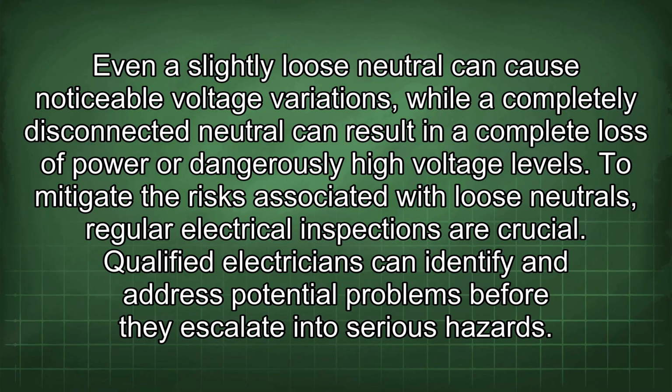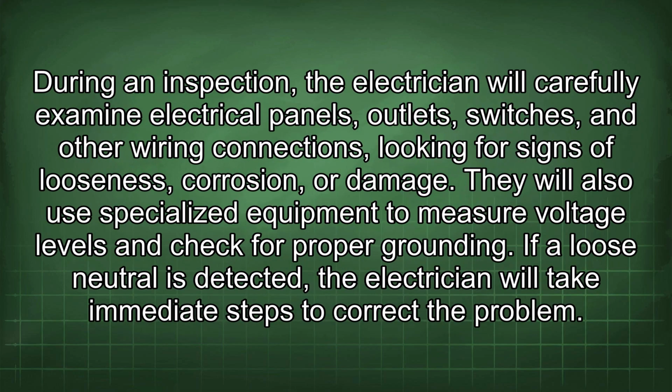To mitigate the risks associated with loose neutrals, regular electrical inspections are crucial. Qualified electricians can identify and address potential problems before they escalate into serious hazards. During an inspection, the electrician will carefully examine electrical panels, outlets, switches, and other wiring connections, looking for signs of looseness, corrosion, or damage. They will also use specialized equipment to measure voltage levels and check for proper grounding.